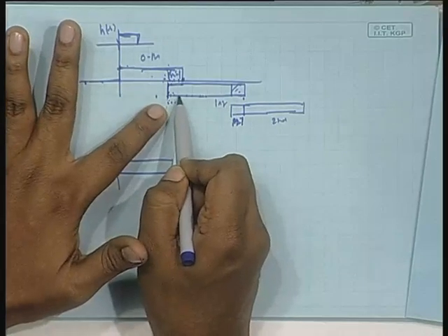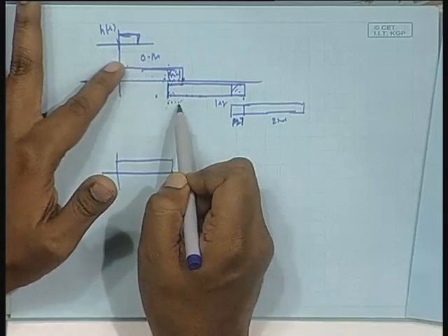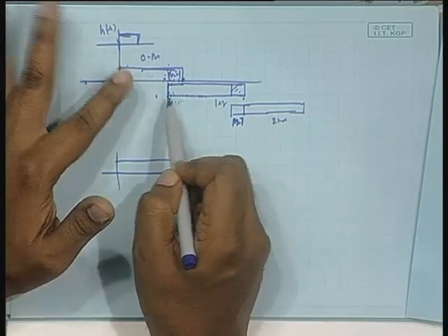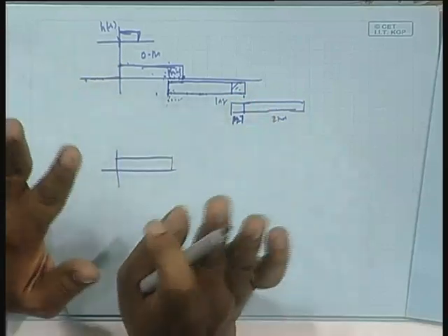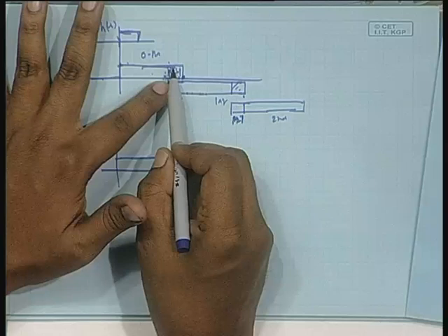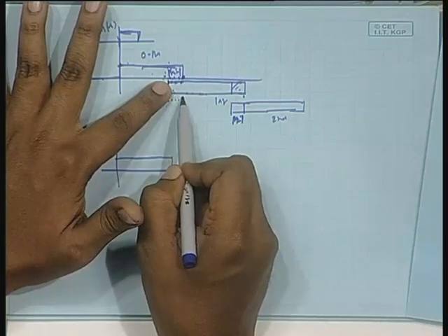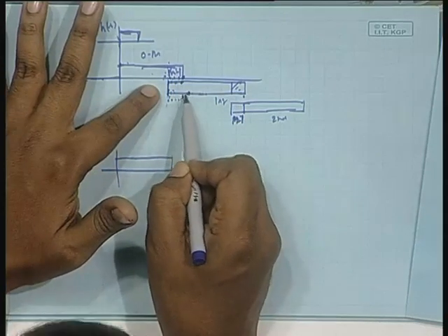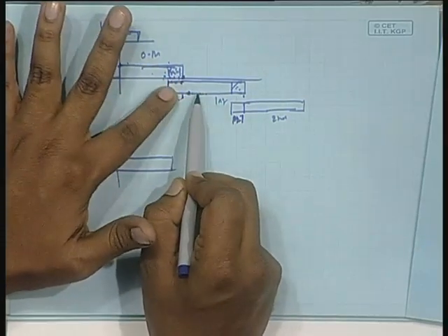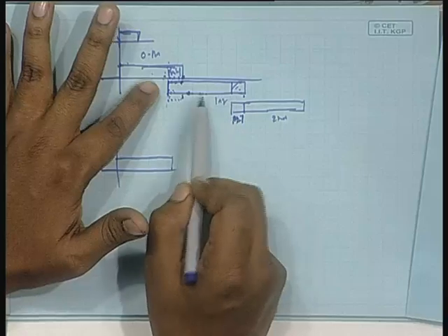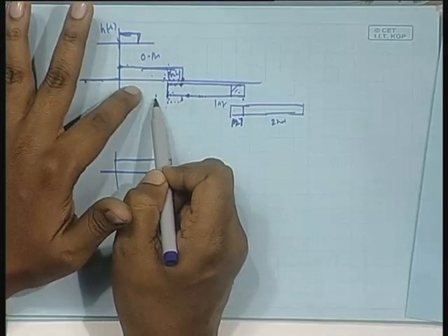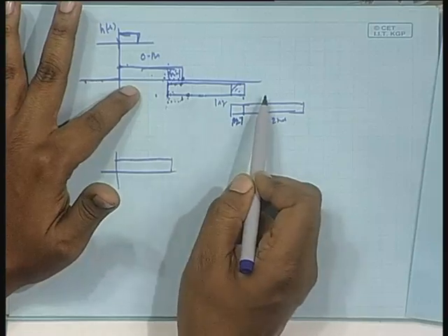Firstly, these points give me a wrong result, even if the weights did not change. Now the weights also have changed. So at these points I do not really want the output. Are you getting me? I will not need them, because the correct desired values are already computed. I will throw them away. But from this point onwards, I need the output for this block only, with the filter weight obtained for this block, and for that I do not need any data from the left of this. So that is available and I happily do it.